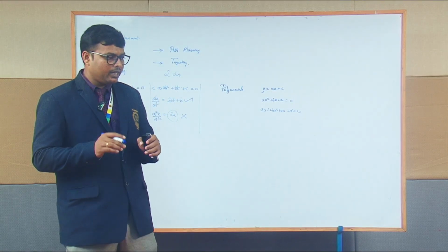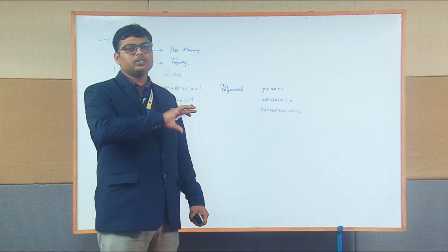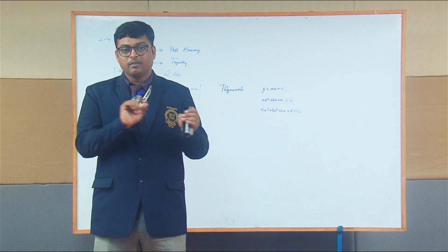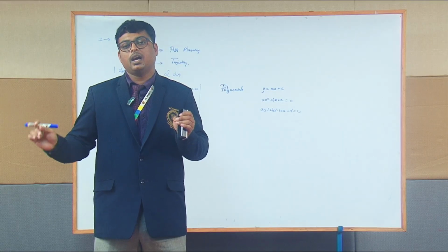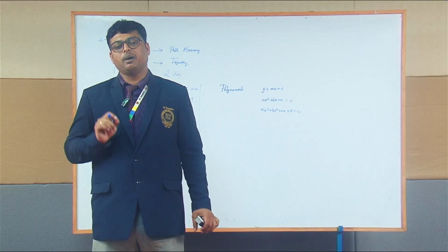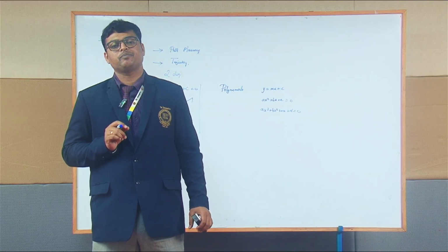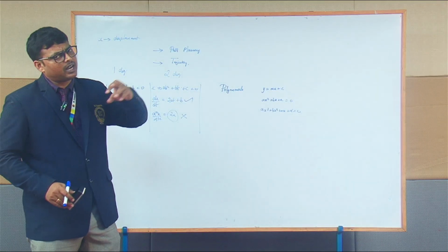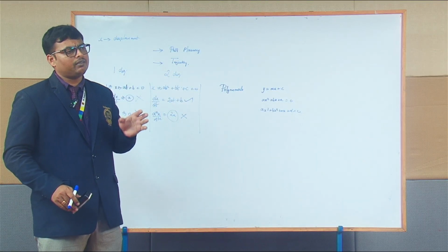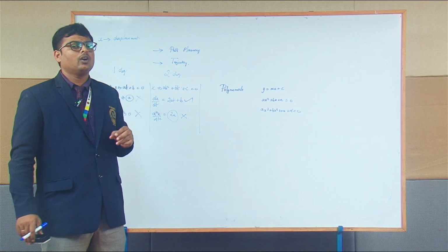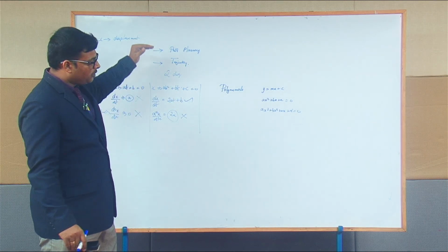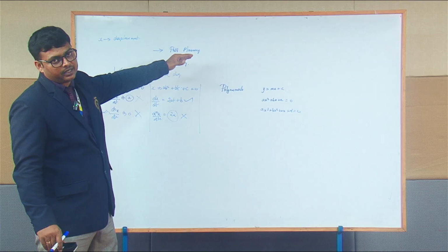If I am creating a path for the robot, this path should have a starting point and destination, which is governed by the equation, and the governing equation should be a minimum of a cubic polynomial. In path planning, we also have smooth transition planning and spline trajectory planning. All these are subparts that need to be learned when we go for path planning techniques.